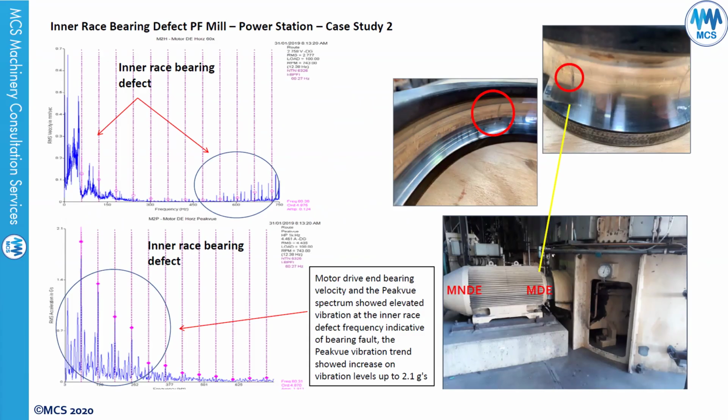software and enter the running speed for the shaft the bearing is attached to, and you put the bearing number. Then the software will automatically calculate the forcing frequencies, and they will be added to the software as input fault frequencies, which you can view when you're doing the analysis. That makes it easier when you choose the bearing type, or when you want to view the fault frequencies, and they can be lined up and matched with any of the non-synchronous frequencies.